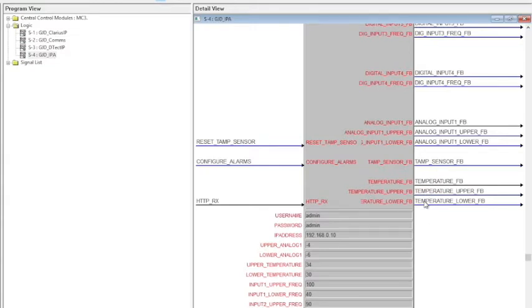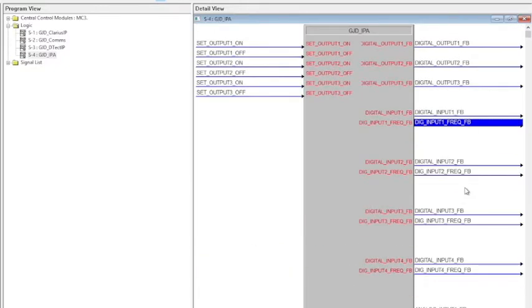levels have been exceeded. We haven't provided a touch panel design for these modules, as they are most effectively evaluated in Simple Debugger. Simply run the project in Simple Debugger, then you have full access to controlling the signals and monitoring the various events that are being received.